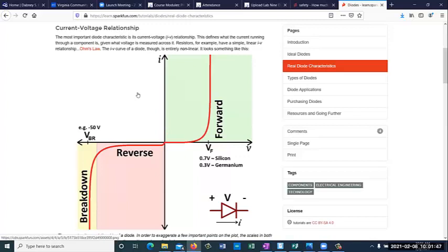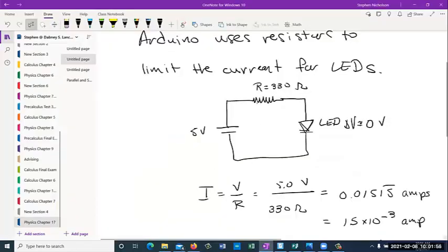So that's, but you can't use Ohm's law here for the diode because it's not linear. But you can use Ohm's law for the resistor, which would give you an almost iterative thing here. You'd figure out what the current is based on the resistance. Then once you get the current, you can calculate the voltage drop across the LED, which leaves less voltage across the resistor, and you go back and forth until you reach some final solution that would satisfy both of those requirements, both the linear Ohm's law for the resistor and the other type for the diode.